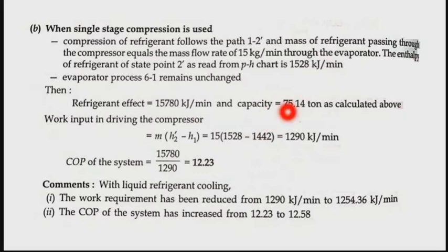So that is why the COP changes, but there is no change in the refrigerating effect. Whether you are using a single stage or a double stage, there is no difference in the refrigerating effect. The only difference will be in the COP of the system and the total work input to drive the compressor.